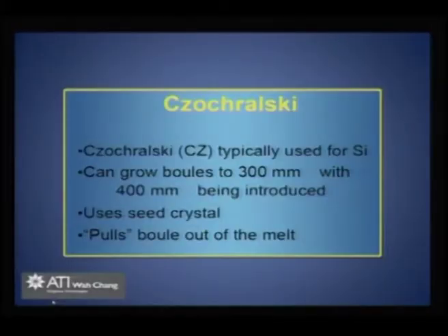Therefore, this is one of the established ways to grow that crystal, and if you have a feed, you can realize a single crystal successfully for 3/4 of the batch that you are feeding. Therefore, you do not lose on the starting material, because the silicon powder itself is very costly.